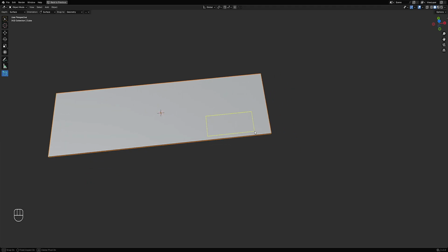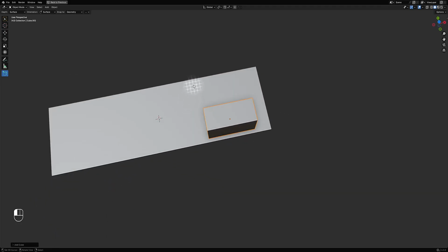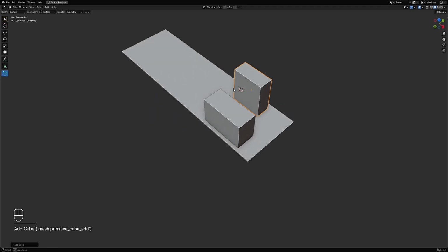It will follow the orientation of the face, and then use its normal as well to further align the face to follow the rotation or orientation of the face based on the global axis. Okay, so you can draw like this. Then the second mode will be to extrude or assign the thickness to the cube object.